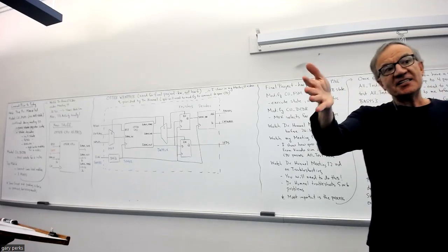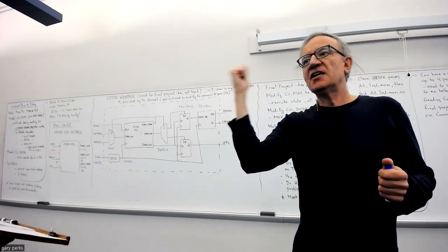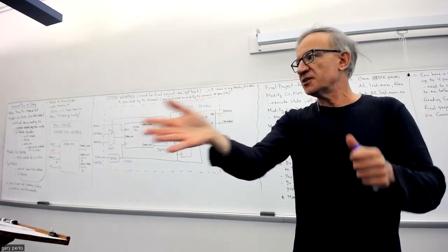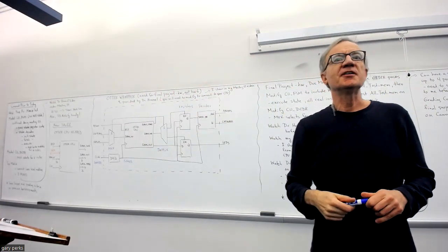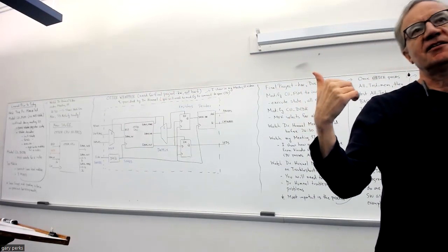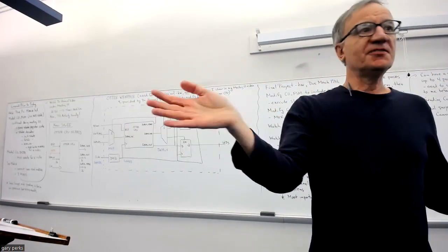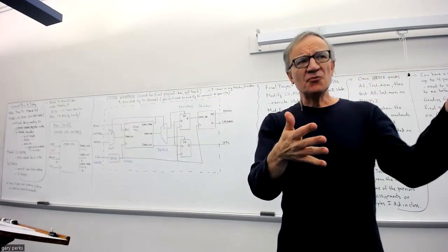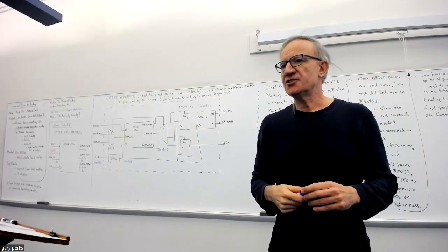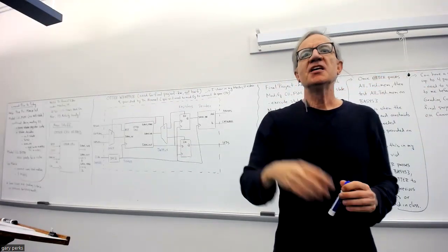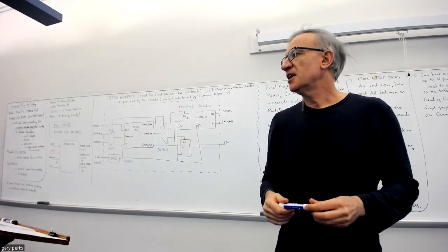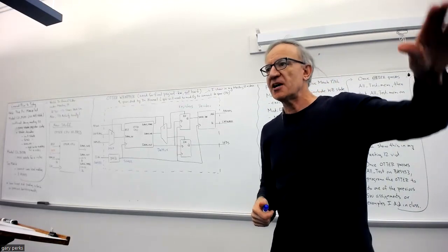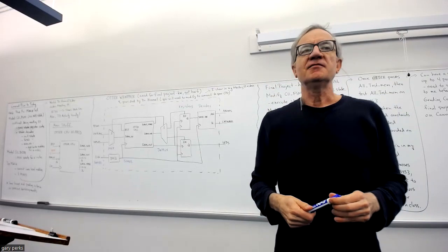Now you have to test to see if it works on the hardware, basically, whether it's working with the wrapper on your Basys board. With my design, that was fine. But when I went to program it with one of the exercises that we did during the quarter using some switches, it wouldn't work with that program, even though I knew the program was fine because I tested the program out on RARS.